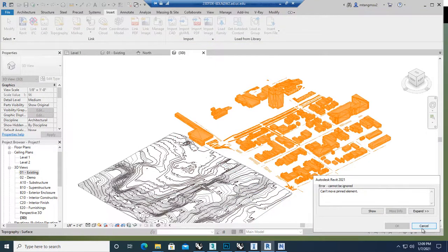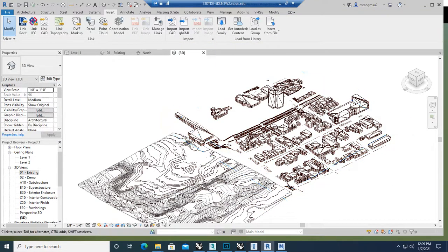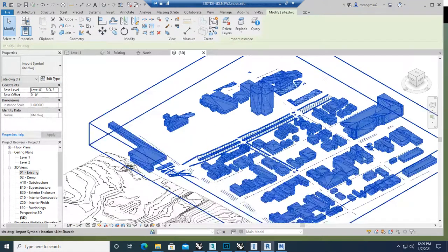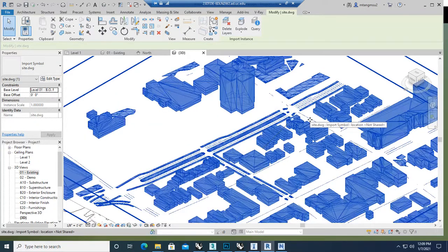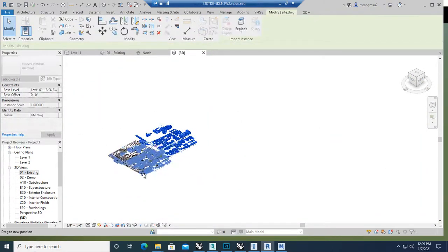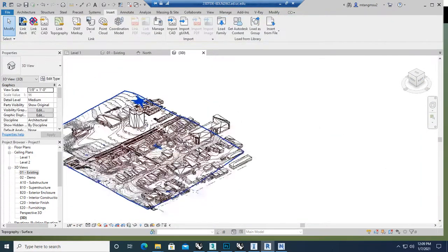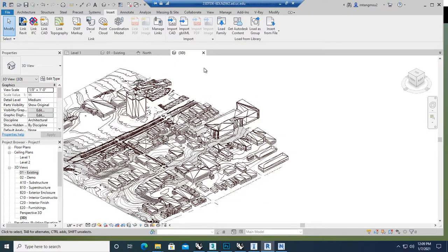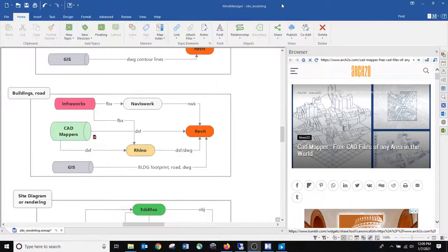Okay, can move that around. Oh, I think it's locked. So you have to unpin the geometry. Can't see where is the pin. Oh, it's right here. So click, you can unpin. After you unpin the file, then you can move that around. Okay, so this is another way you bring in the DWG or DXF into the whole pipeline, into Revit.